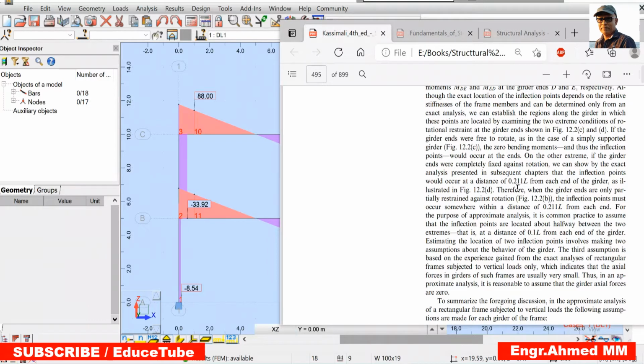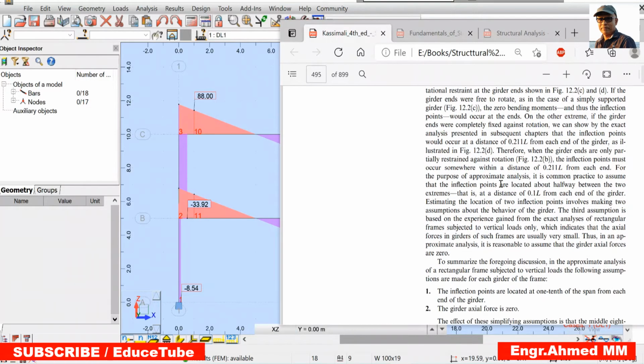Then we can say 0.211 L. But here we are assuming that it is only partially restrained against rotation. So the inflection point must be somewhere within a distance of 0.211 L from each end. Somewhere within. That is why it is taken as 0.1 L.